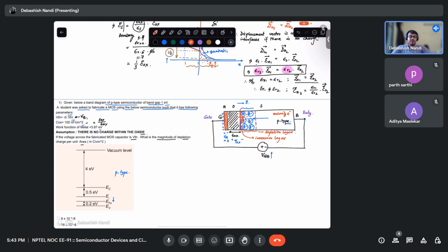So what we have, when we apply a positive voltage on the gate for a p-type substrate MOS structure, is two kinds of negative charges to compensate those positive charges on the gate.